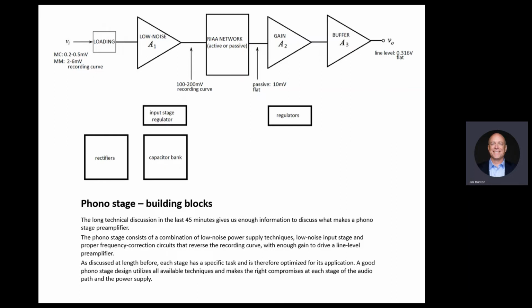Or you may have just a resistor capacitor network that forms the RIAA response, what we call passive RIAA. So we have a stage as an amplifier. It goes into a filter with resistors and capacitors. And what comes out here is corrected levels. So the bass through that network comes out at a higher level than the treble.